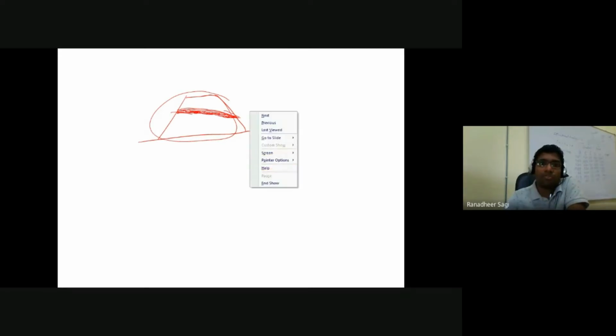As the process takes place, a large void path gets formed, resulting in what is called a hollow cross section. This complete region is getting emptied, and the strength of the embankment relatively decreases, resulting in a possible mode of failure. We have to understand that very clearly.